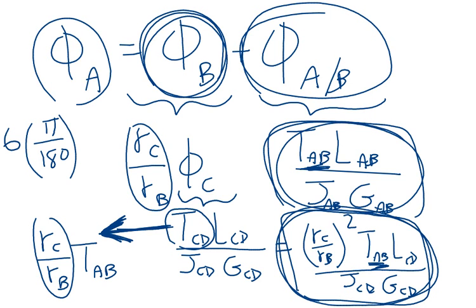And then you're going to say that's equal to these two terms added together. Okay? And what would be the only unknown in these two terms? It's the torque. So that would be another variation of the design problem, where you know what the maximum rotation you want to allow is, and you're going to solve for the torque that could be applied.